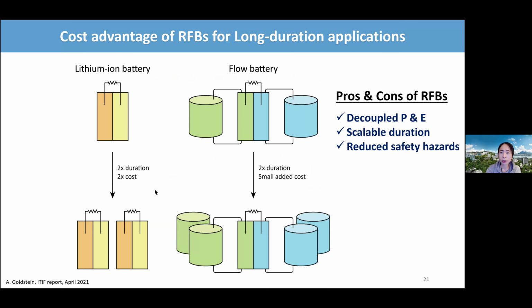And like I mentioned, if you want to double the duration in the case of lithium-ion battery, you will just double the cost to buy 2 sets. But for long duration using flow battery, you can have added small cost using the electrolyte tank.